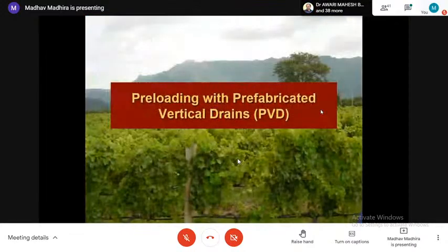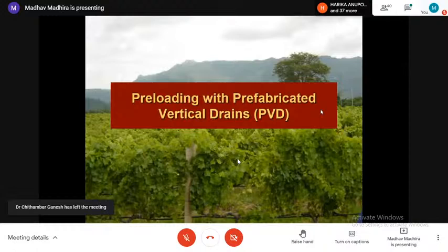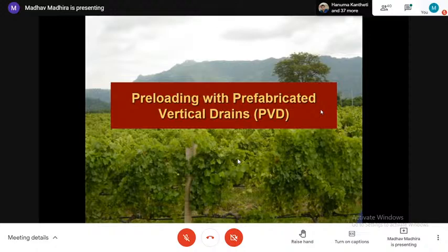Let's see these particular cases. I would like to illustrate them with different case histories, mechanics and procedures. As I said, the cheapest and the best for most soft clay is preloading with prefabricated vertical drains. In the good old days, we had sand drains, which are time consuming to install. Now we have PVD, which I can install within a minute or two over a depth of 12 meters.